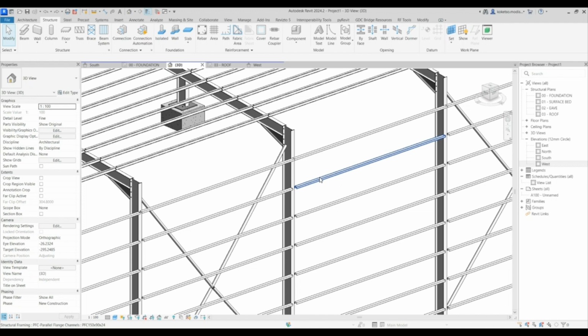So luckily for bracings, it's not gonna take a lot of time, and we're gonna do the bottom ones. So connections, select this bracing, the column, and then the same connections, press enter, right click, propagate connection, and then they're going to be copied towards the other connections, the other members. There you go. This is what we have.